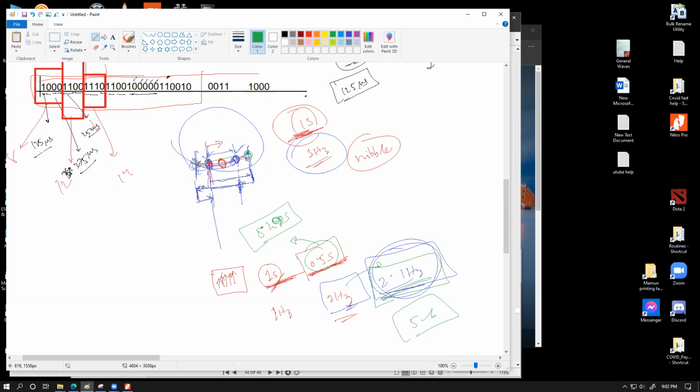And sir, if we use 2 hertz, we can observe it at the terminal position, right? Not necessarily. If you use exactly 2 hertz, then you'll be seeing 2 alternate positions continuously. As in the same ones, yeah, we'll be seeing at those 2 positions continuously and alternately. Because it would take exactly 1 second to go back and forth. So that's why, sending a sequence of 2 hertz, I mean, let's say you're sending 2 pulses per second.